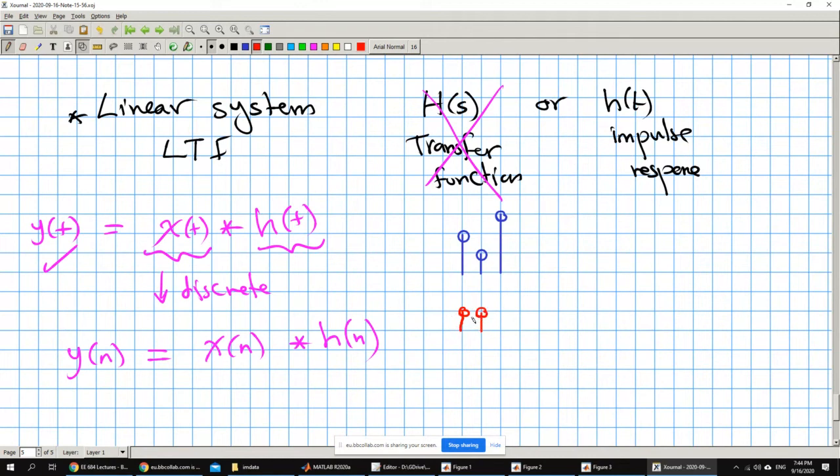Okay, what you usually do is basically, this is x, and this is h of n. If you remember the convolution, we used to take the original version of h of n and flip it. Basically, if this is 0, then I'll flip it with respect to 0. So it becomes like this. Multiply this and this, and compute the output. I multiply this by this and add, and then compute the output.